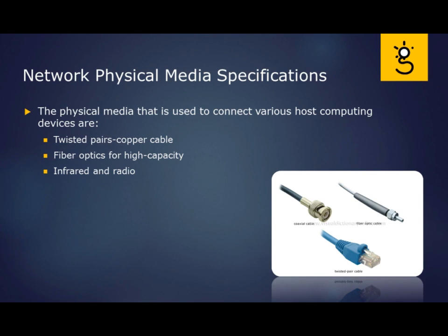Now, your copper cable doesn't get to run very long. Believe it or not, even though you're sending electrons down this copper wire, and they're going to go really fast, not quite the speed of light, as they're going down, they're going to get tired because there's still energy being used to go down that copper wire, right? It's just like you running a race. You might start off strong, but you're going to start to wear out at the end. And so there's a limit to the length. That limit is called the attenuation, when the signal gets weaker and weaker and weaker to the point that it's no longer really something we can use. Most often that's about 100 meters in most of the copper solutions.